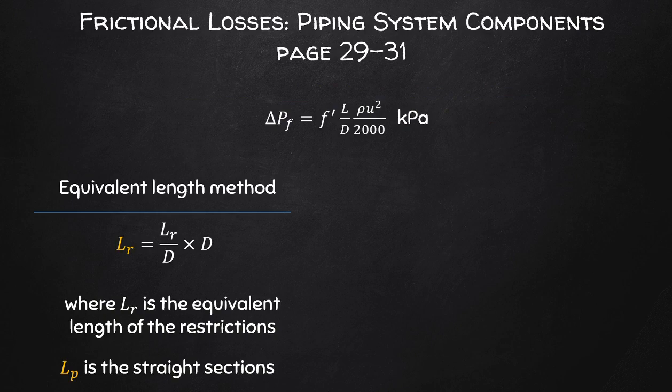So in the previous exercise, it was shown that the friction factors can be determined for straight pipes using various means, and it is really up to you to decide which options you want to make use of, or which options are available for use. Design is often open-ended, and there aren't always guidelines to help you in these sorts of decisions. If you consider the Darcy-Weisbach equation, what we have in essence is we have to determine the f prime term. Okay, so this is what we have now kind of been having a look at.